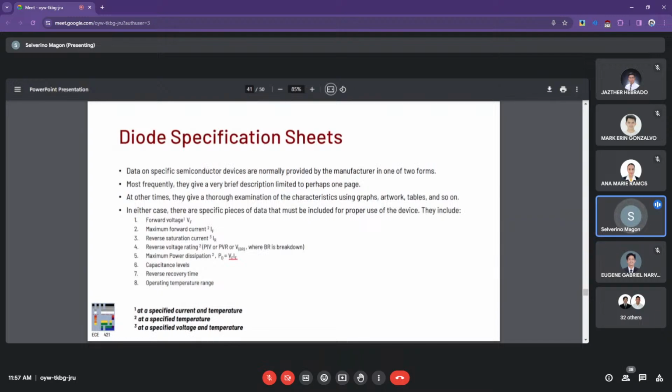In some cases, if you're working with higher frequency applications or filters, you need to consider the equivalent capacitance values, no? Because we're dealing with semiconductors, and in some cases, insulation properties resemble these devices in high frequency applications. So you need to look for these figures as well.